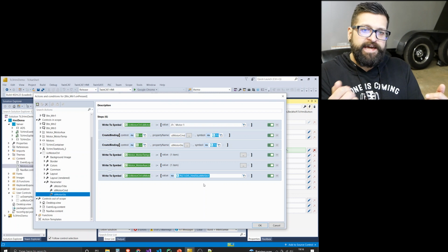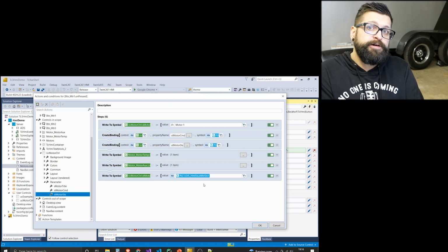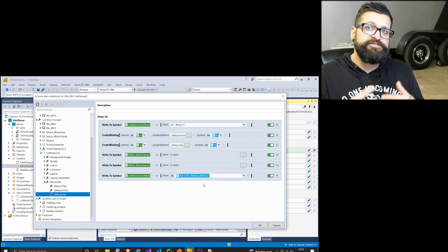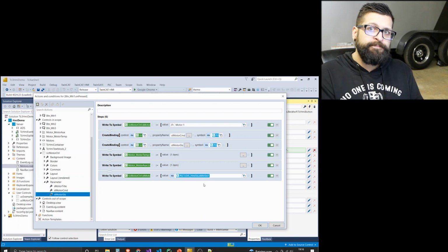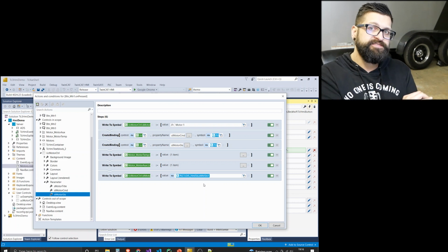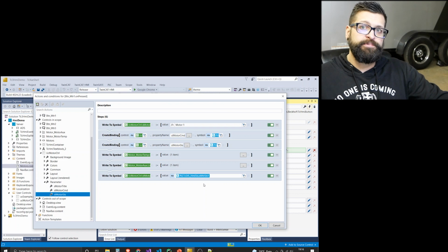user control, and it's going to display whatever the active value is at the time that you triggered that event. It's not creating a living binding that is updating as time goes on. It's just saying you triggered an event, you pass the values into this user control, I'm going to display the values at the time that they were passed in, and there's no link back and forth between the HMI and the PLC now.